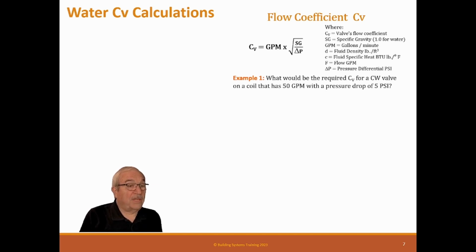So all of a sudden you have less control, and then pretty soon it can get really bad because it's not linear. So the valve may not see its control until the valve gets 50% closed. So now you've only got 50% of the throttling range you had before. So this is really important. It shouldn't be just a set PSI. It should follow the load. And that's how it should be. But, changing minds is hard to do sometimes.